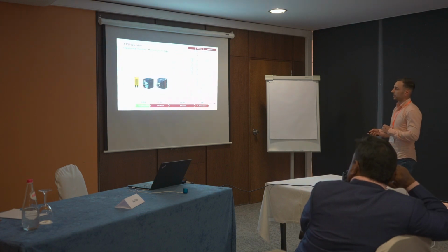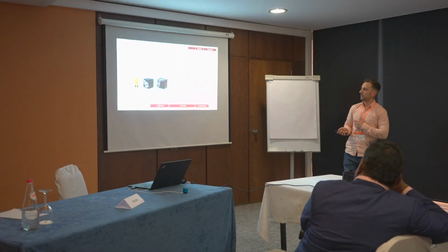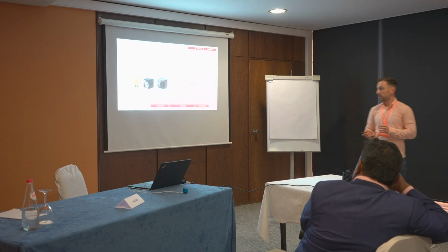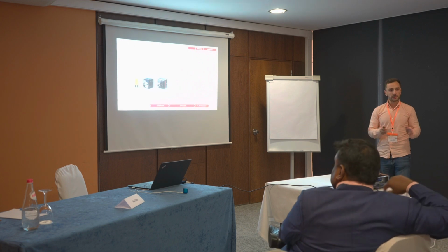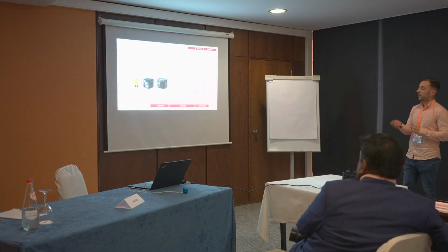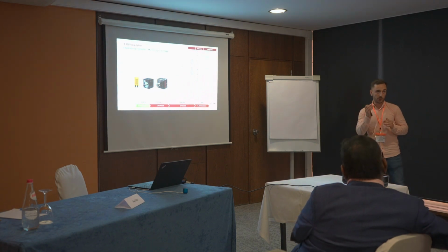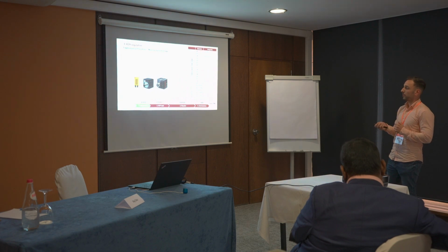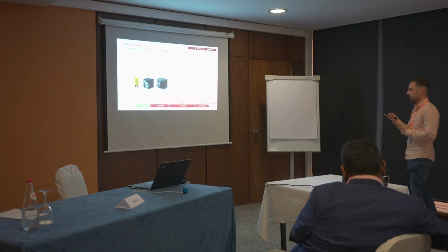Regarding the monitoring system, we are using 15 strain gauges distributed in the structure. 2 accelerometers are also placed in the front of the vehicle, and the lateral side of the driver side is also monitored using digital image correlation. This is the camera to acquire the video recording.